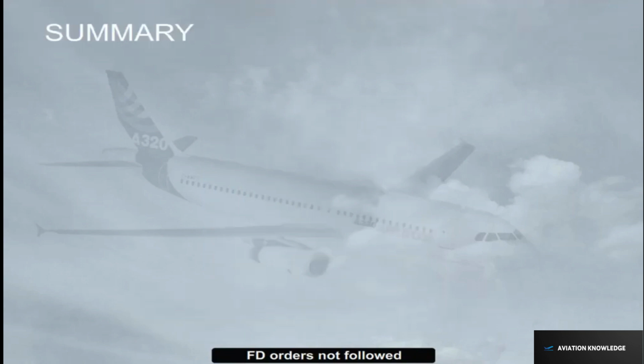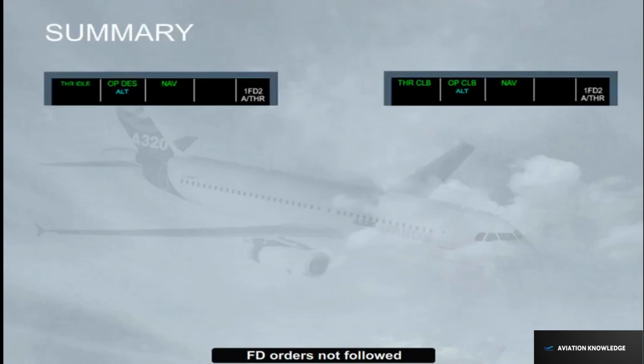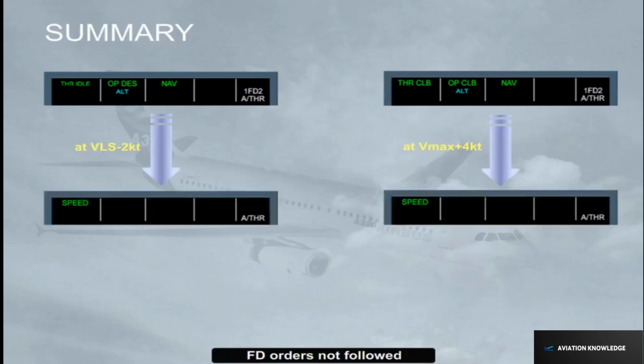The flight envelope limit speed protection with flight director on, autopilot off, is done by autopilot or autothrust mode reversion so that at minimum speed or at maximum speed, the flight director bars are removed. Therefore, the autothrust reverts to speed autothrust mode in order to regain target speed.